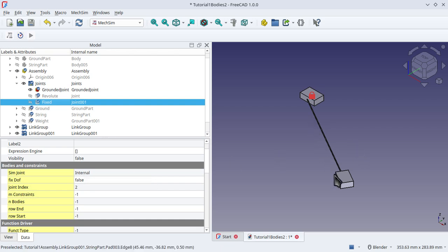And the center of mass of this entire joint is calculated as the sum of the center of masses weighted according to the weights of those two parts of the assemblage, etc., etc. So automatically this has now become a system with one less joint, because we've taken the fixed joint out and made this into one object.